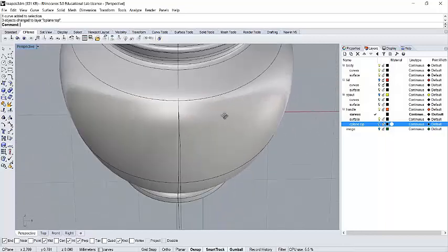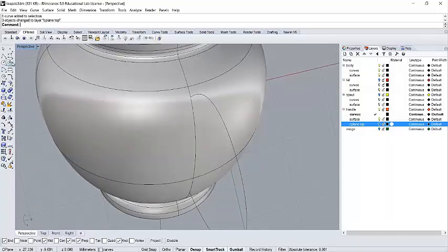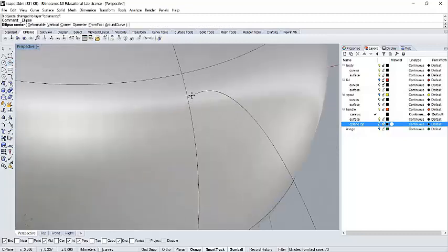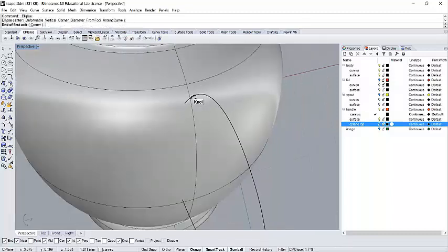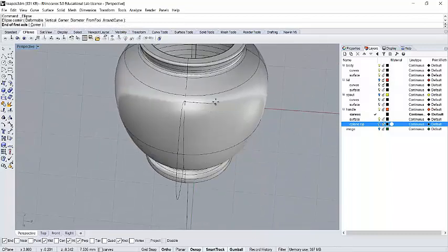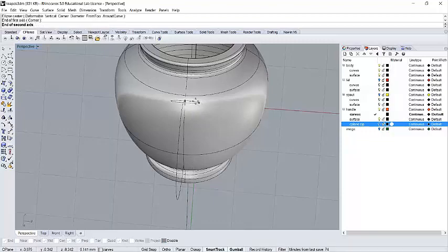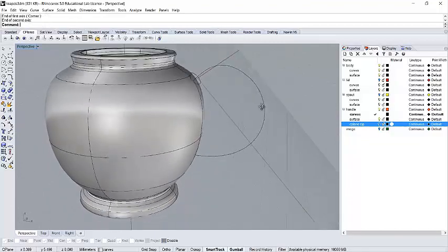Okay, so with that I can now center. I'm actually going to try and snap using nearest and get quite close to this surface. Doesn't have to be perfect. Now I'm holding Shift, which locks me to ortho. We covered this earlier. In fact, I'm going to disable all of my snaps for now, so I can create that shape. So you see how that worked?